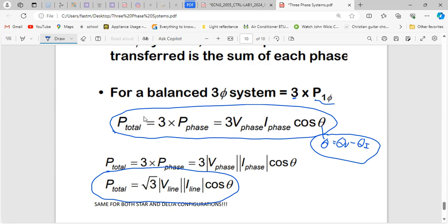So like if you have, there's your phase voltage, I'm trying to say phase current, sorry. Yeah, so if I give you a phase voltage of like 30 degrees and a phase current of like 10, your theta will be the difference between them. Yeah? It's just the angle between your phase voltage and your phase current. So you learn something. All right, so these are your two equations for power.